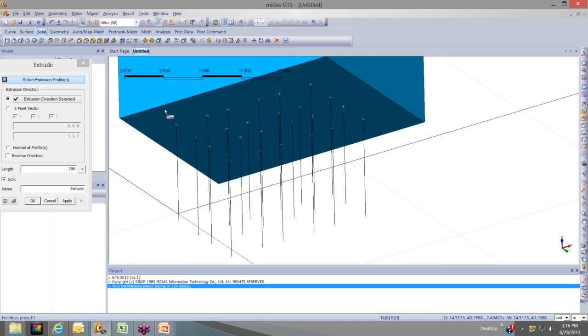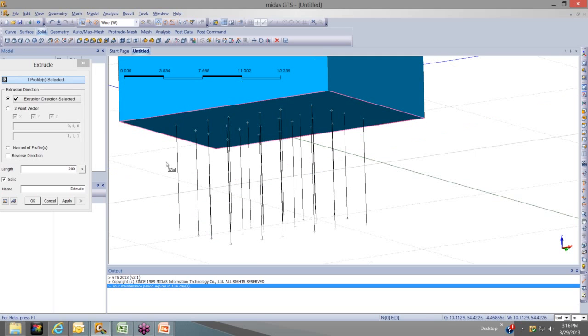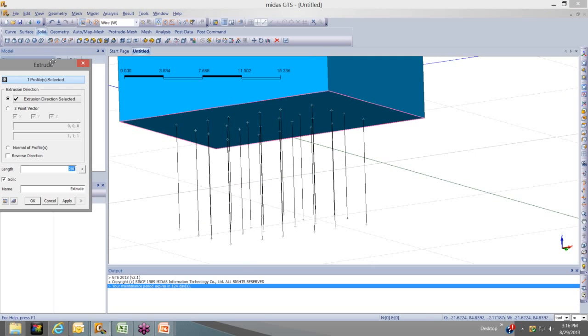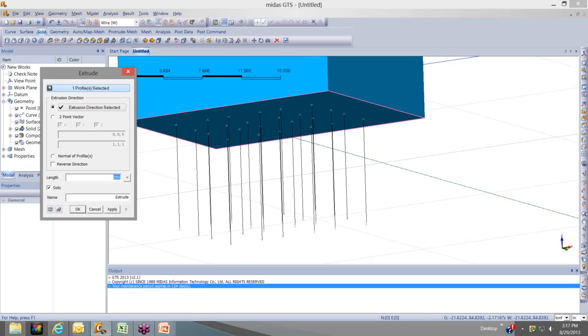When you're selecting the bottom layer here, or the bottom wireframe, just go to the corner, and then you just have to navigate the cursor up to a certain edge where it'll select the wireframe. So this can be a little tricky, as you can see. I selected it a couple of times, but I keep moving over it. There it is. So now, just create the length, which I believe is 0.6 for the raft. Check on the reverse direction, and just name it raft. Okay, there we go.